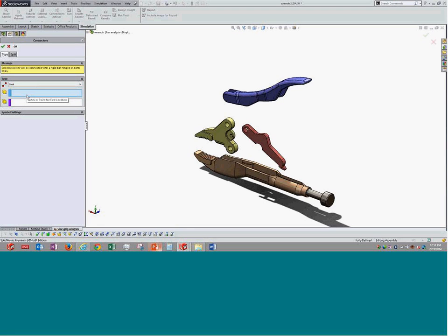We are saying that one particular reference point on one part carries any other reference point, and no kind of relative motion between these two points. So this could be one thing, and the other could be the rigid links, wherein we have a broader aspect: we can select faces to give the rigid connections.